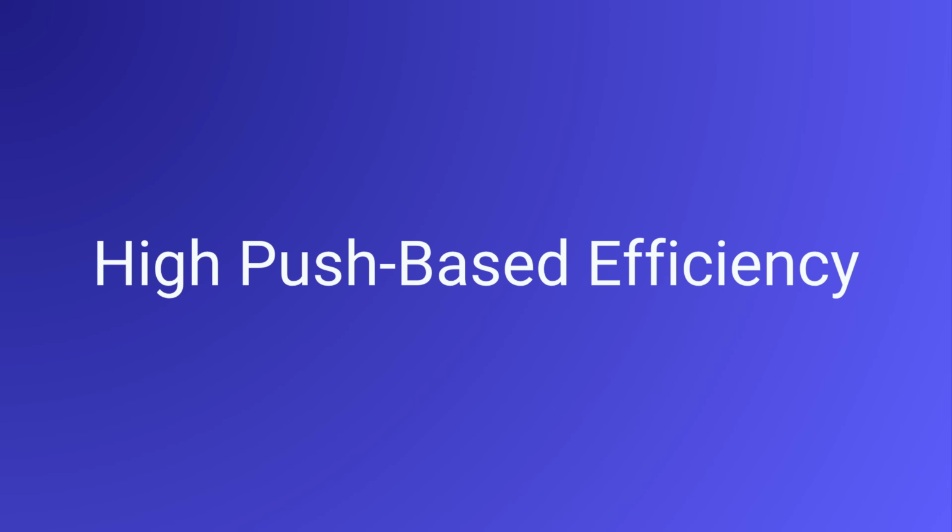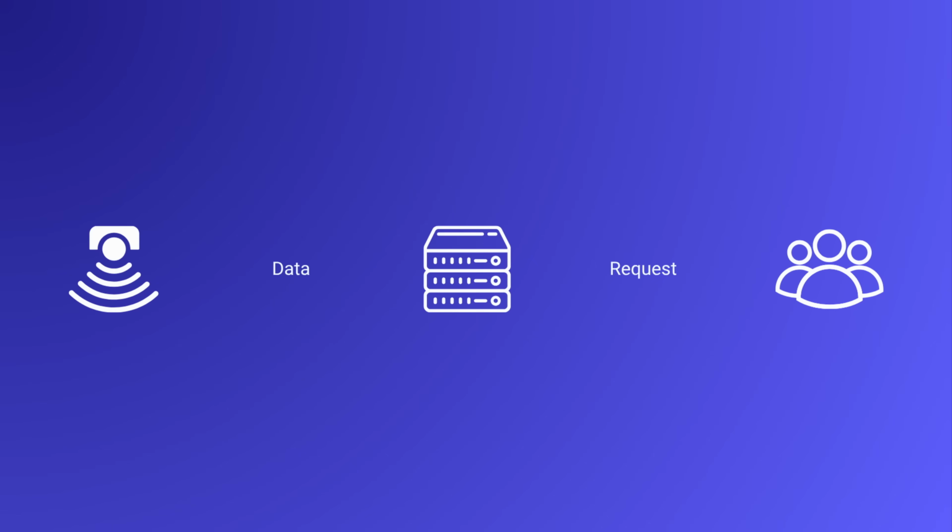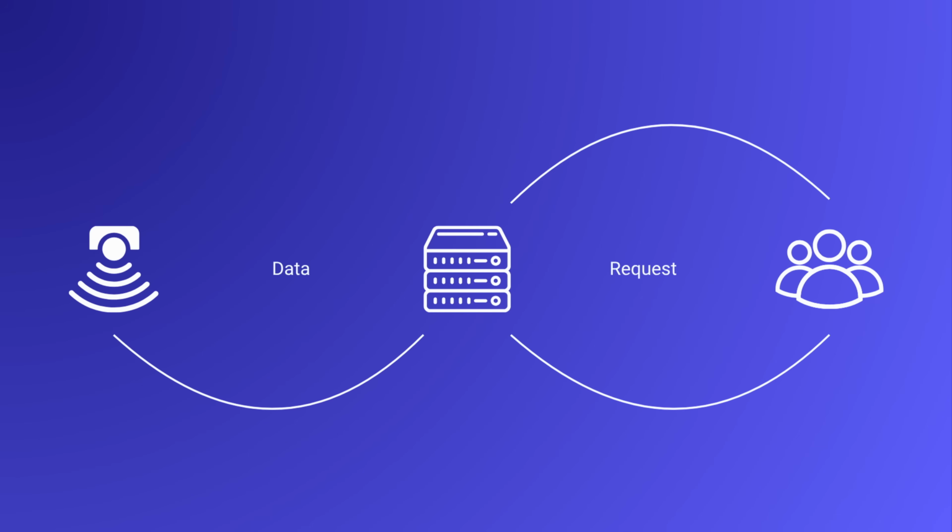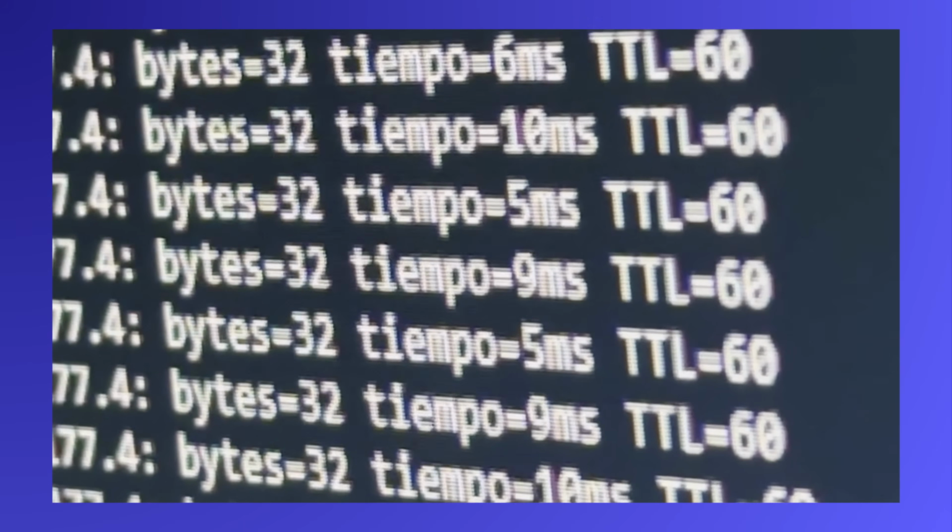Efficient push-based subscriptions. Now, OPC UA has a publisher and subscriber modality. What that means is that you can have a server say, hey, I have this information that I can publish as a temperature read. And then on the other side, you can set up a client that says, hey, I want to subscribe to that information. The server then pushes notifications only when those values change, at specified intervals, or when you trigger a call. And that's super bandwidth efficient and latency aware.